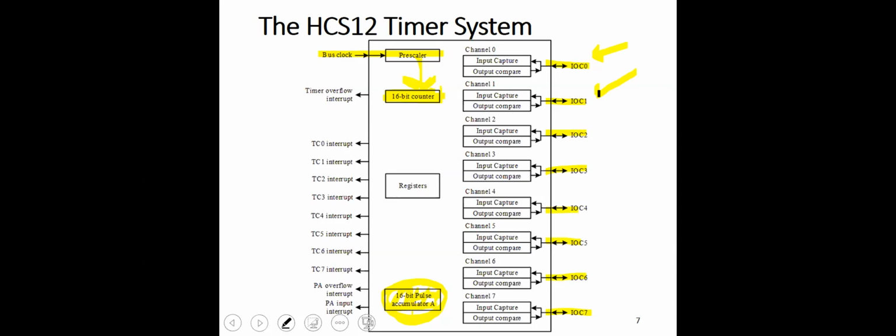If we configure a pin for input capture, then it will be configured as input, and whatever happens on this pin, such as a falling edge, rising edge, low level, or high level, can be configured to capture the value in the timer and store it in a special register. So there is hardware here that can be configured to capture what is going on. When something happens, according to the configuration, the timer value is captured and stored in some register.